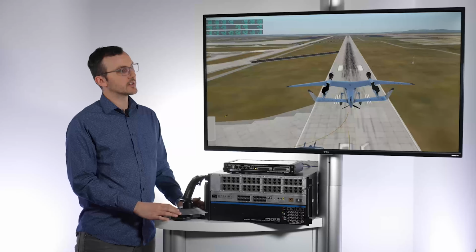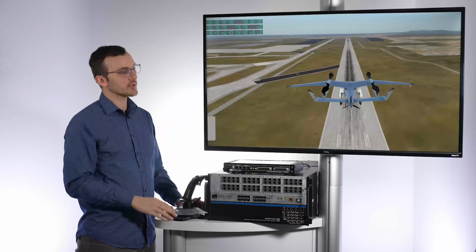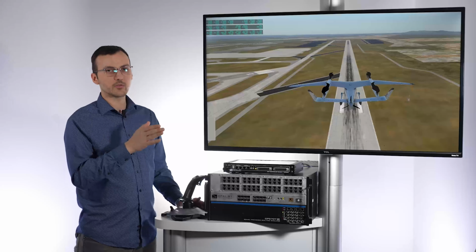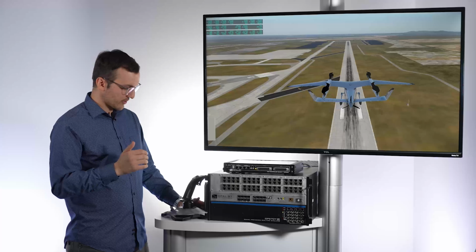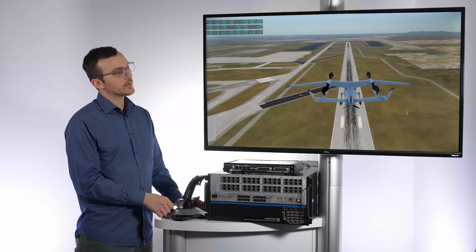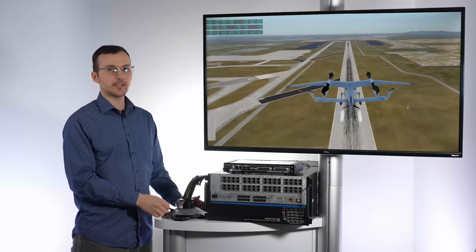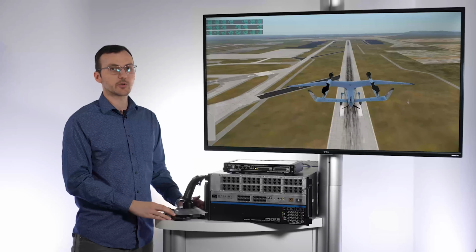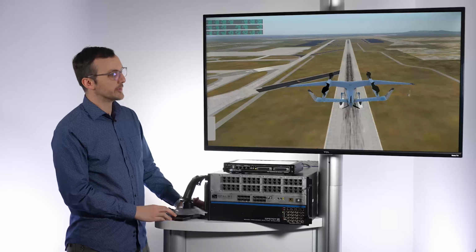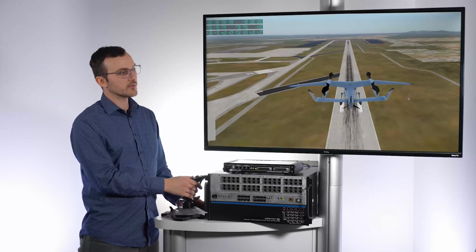So we have 2 modes of running the airplane. One is in vertical and the other one is in propulsion mode. So at the moment, only the 4 motors are running. The 5th one, the horizontal one, is stationary. So we have control over the 4 motors through this lever. We can lose some altitude by decreasing the levers. This will effectively lower the running speed of each one of the 4 motors, which should make the aircraft lose a little bit of altitude. When we're ready to fly, we have a button to switch into propulsion mode.